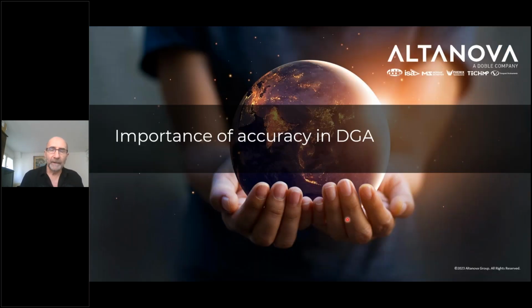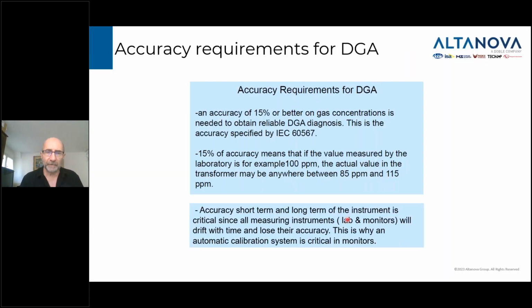Now, why is accuracy important in DGA? The IEC 60567 spec says that the accuracy should be less than 15%. Every instrument has an accuracy range, plus or minus 5, plus or minus 10, and that depends on a lot of different factors. But to do a very good DGA diagnostic using the diagnostic tools that have been developed over the last 40 years, you have to have your system accuracy less than 15%.